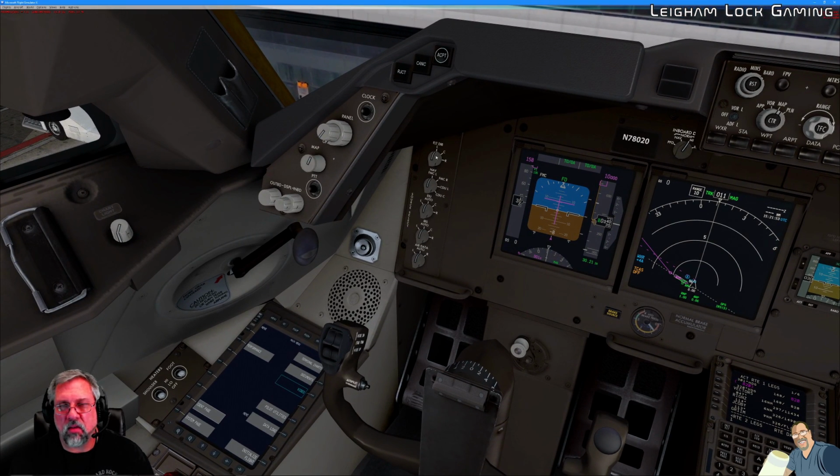For the captain, everything is left, right? Flight director left, navigation FMC is left, the EFIS ECAS auto select is enabled, initial reference IRS is set to auto, and then our air data information is set to auto as well. I kept saying initial; I wanted to say inertial reference system, IRS. Same thing, looking at the navigation display, we can see TCAS off, so that's what we expect to see.